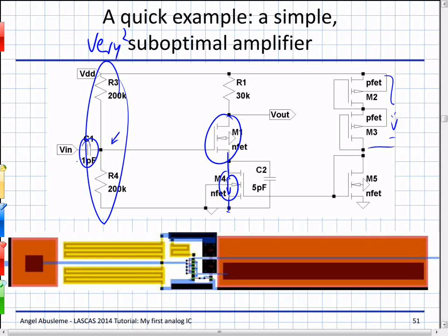That's a coupling cap. So if we want to couple only AC signals, but not DC signals, we want a very large capacitor here. This is basically a high-pass filter. And then we have another capacitor here, which bypasses this current source. So this is a bypass capacitor, right? Bypass capacitor. And we see this layout, which is exactly the same as this thing here.